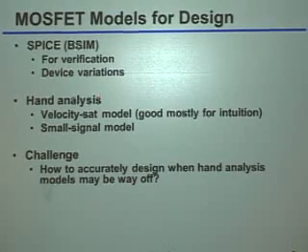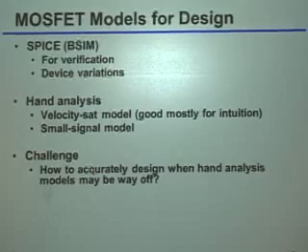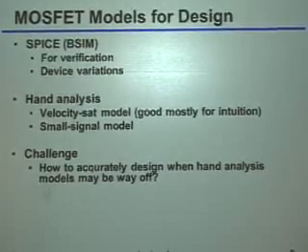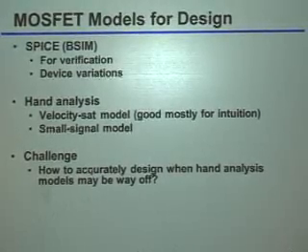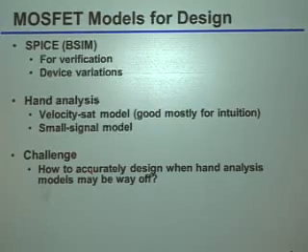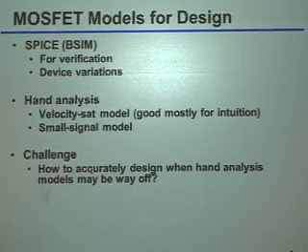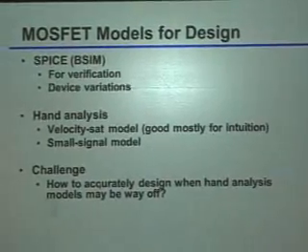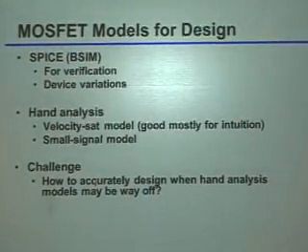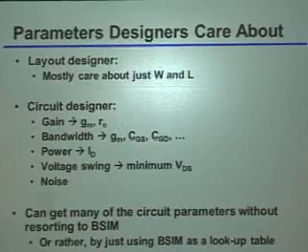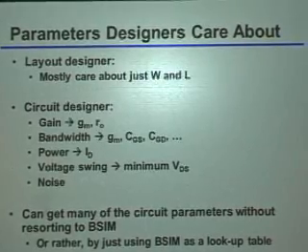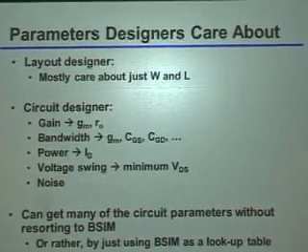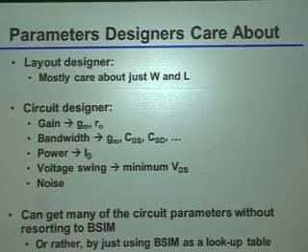Okay? So the question we're going to be addressing today is exactly this challenge: how can we come up with an accurate and reasonable hand design methodology when any typical model that we've come up with, which would be analytically trying to capture the transistor behavior, probably is not going to be very accurate. Okay, so in order to do that, we're going to come up with a methodology where we use Spice as a lookup table.